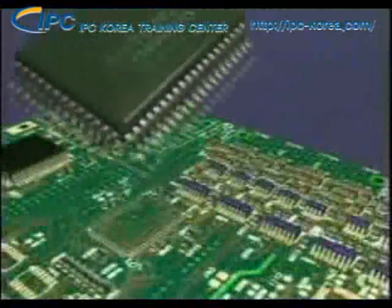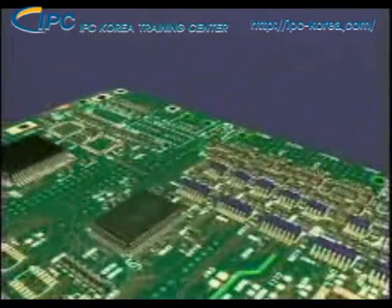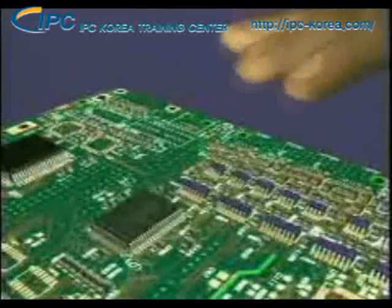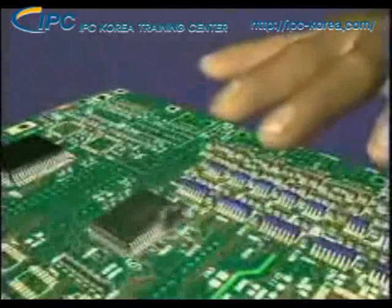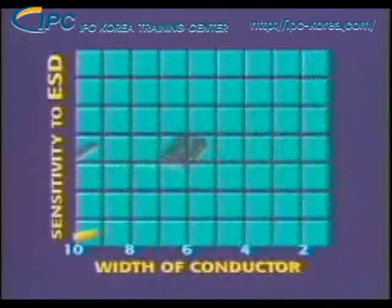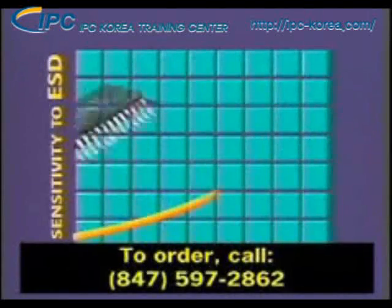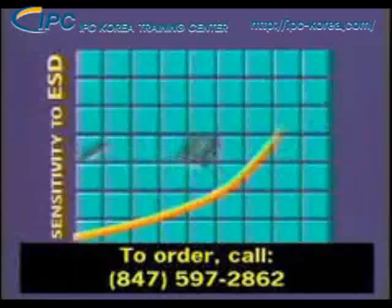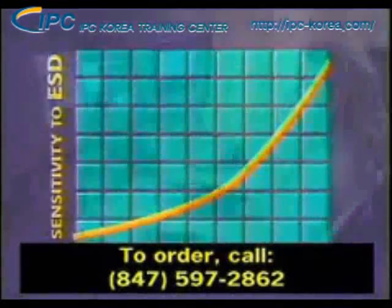Even when the device is soldered onto a printed circuit board, it's still not safe. It can be damaged by a discharge that passes through the board's conductive pattern to the ESD-sensitive component. The amount of voltage needed to damage or destroy varies from component to component, but as these devices become smaller and more complex, their sensitivity to ESD generally increases.